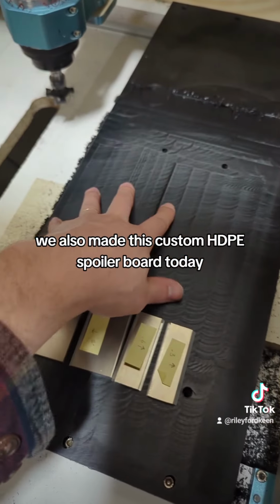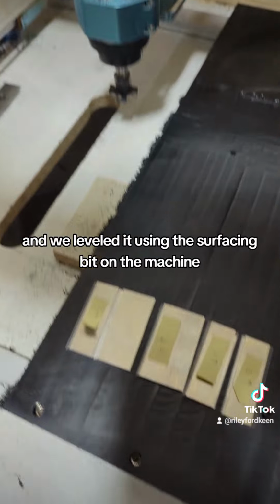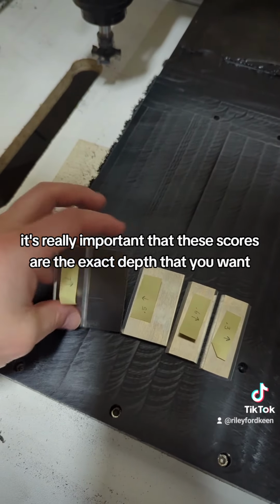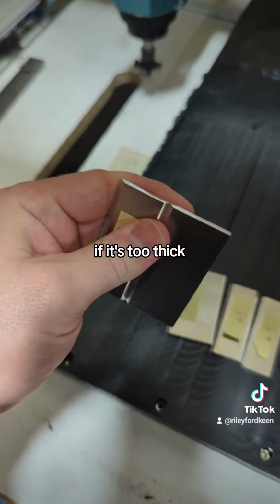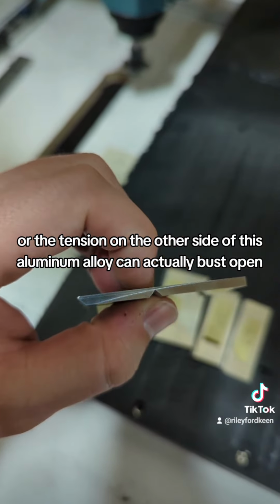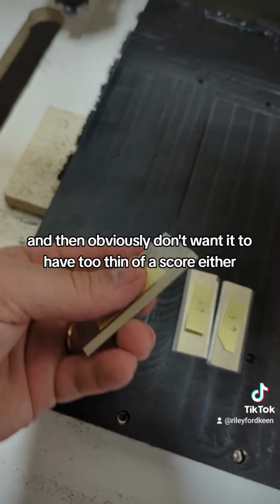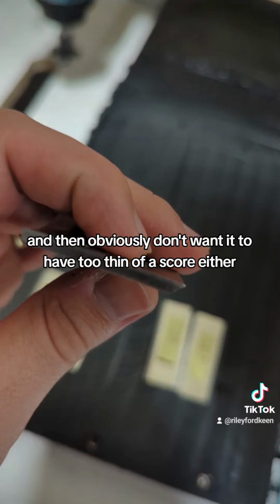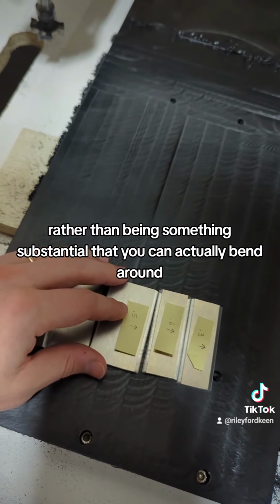We also made this custom HDPE spoil board today, and we leveled it using the surfacing bit on the machine. It's really important that these scores are the exact depth that you want. If it's too thick, it could be hard to bend, or the tension on the other side of this aluminum alloy can actually bust open. And then obviously you don't want it to have too thin of a score either, or then it can be like a film rather than being something substantial that you can actually bend around.